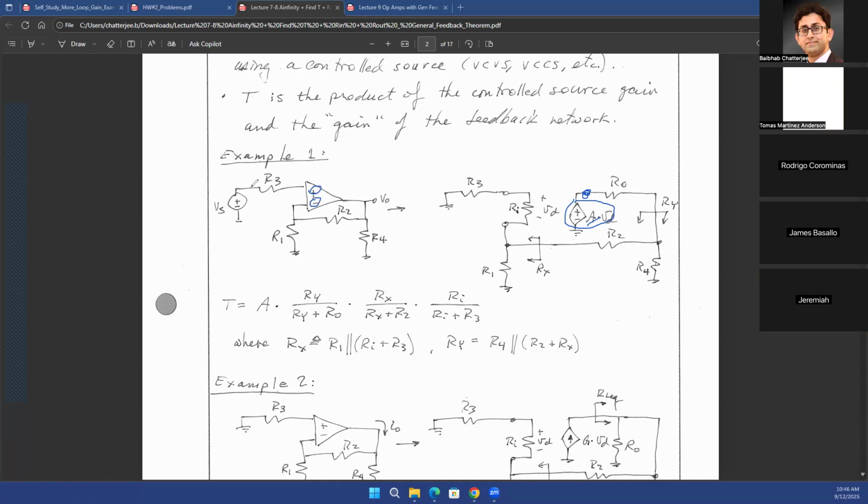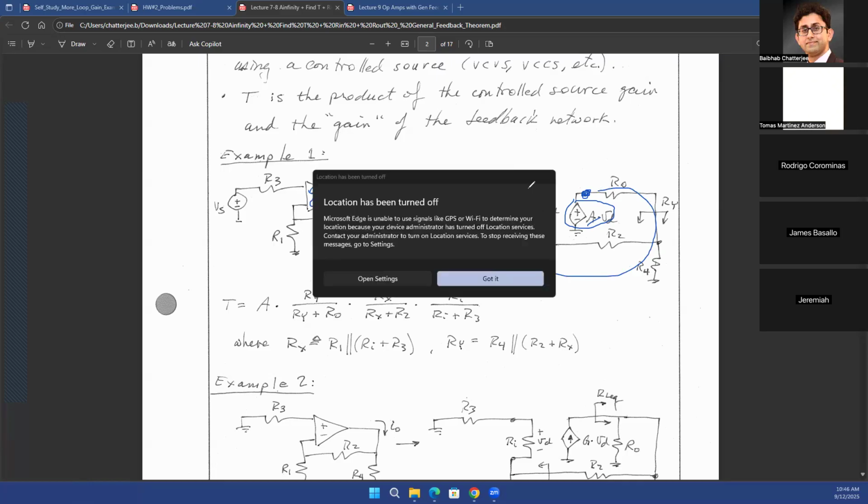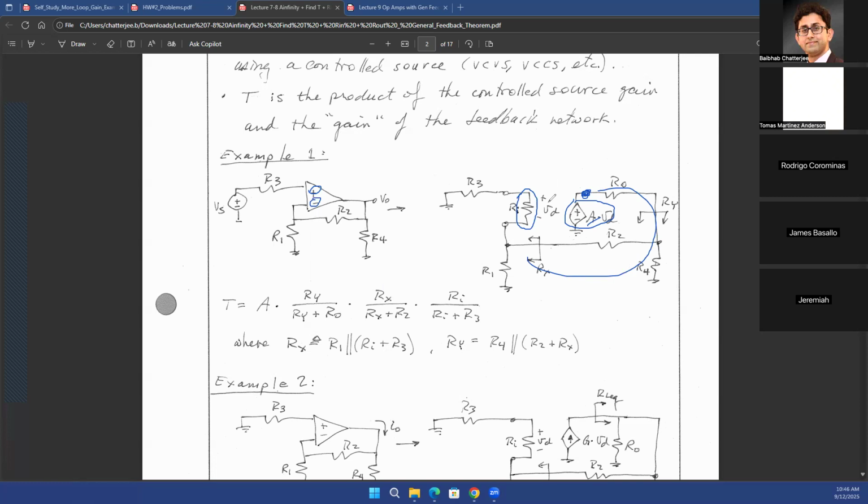We are not talking about the original input voltage source. So what fraction of the output voltage over here is fed back at the input side, between the positive and negative terminals of the op-amp, that is the top and bottom terminal of your input resistance Ri? In the last lecture, we found out how to use these voltage divisions. As you see, there are 3 different voltage divisions in the beta factor or the feedback factor.